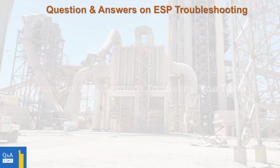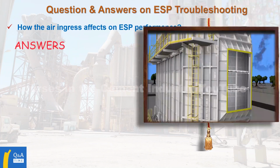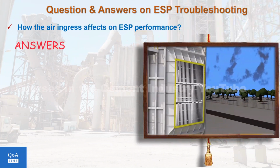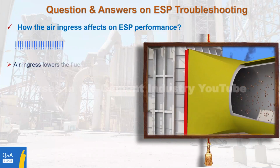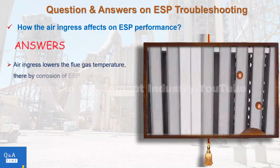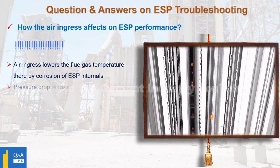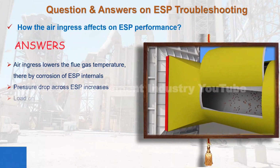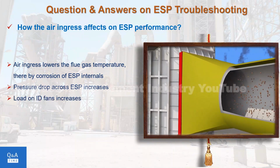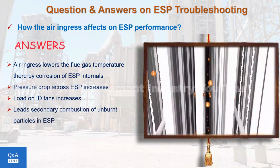Question 12. How does air ingress affect electrostatic precipitator performance? Answer. One. Air ingress lowers the flue gas temperature, thereby causing corrosion of electrostatic precipitator internals. Two. Pressure drop across the electrostatic precipitator increases. Three. Load on ID fans increases. Four. It leads to secondary combustion of unburned particles in the electrostatic precipitator.